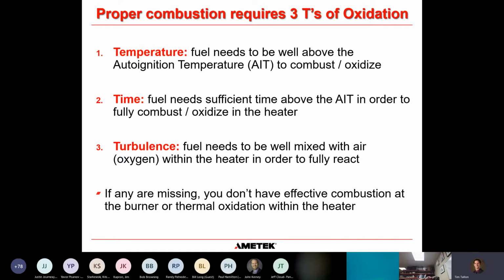The second thing to consider is time. The fuel needs to have sufficient time at or above the auto ignition temperature in order to fully combust and oxidize within a heater at a burner. And third, almost most importantly, is turbulence. Fuel needs to be well mixed with air in order to fully react.